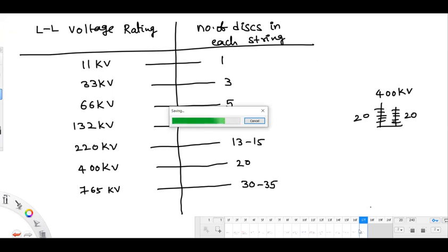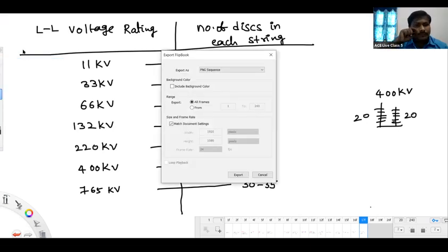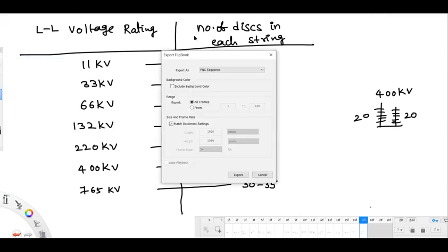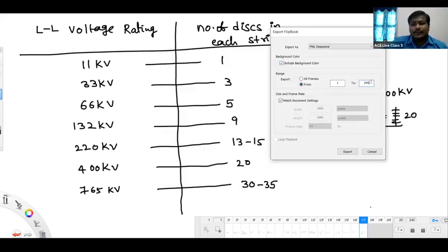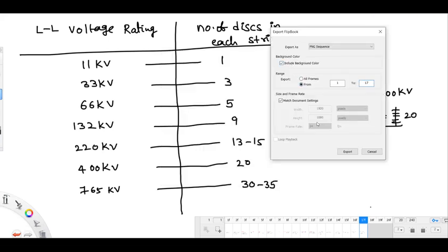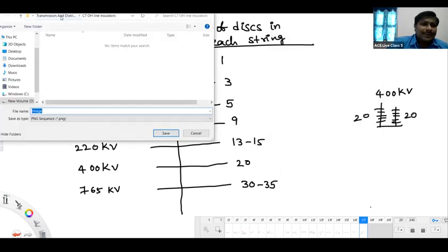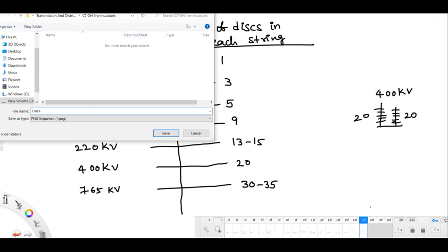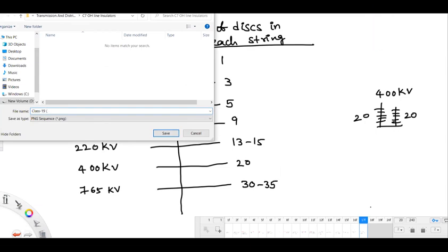Sir, while calculating the capacitance of a 3-core 3-phase underground cable, in the second experiment you connected all the 3 cores together, right? What's the doubt now? In the balanced condition, the sum of the currents equals 0, right? It is not a 3-phase operation there, right? Sir, but it is a 3-phase conductor. A 3-phase conductor only, but you are not applying a 3-phase supply, right? Then all the angles are at 0 degrees, same phase.